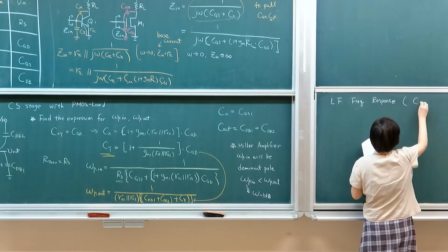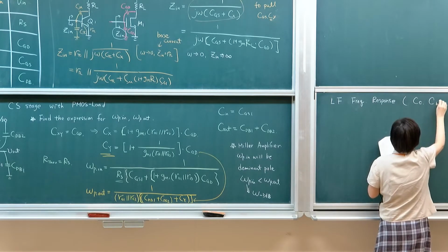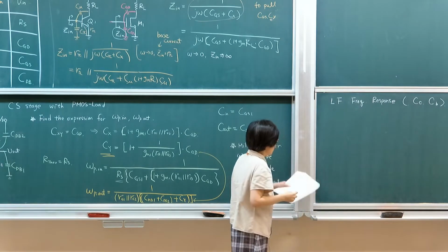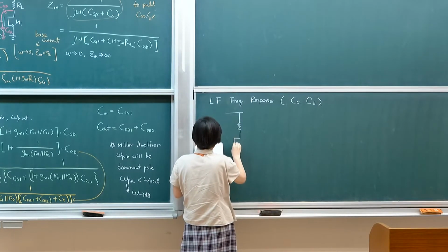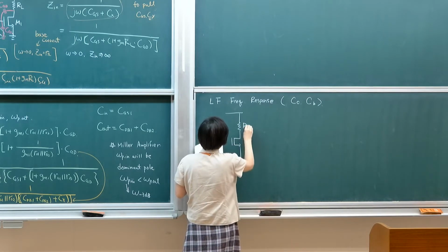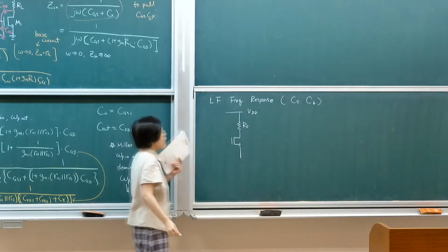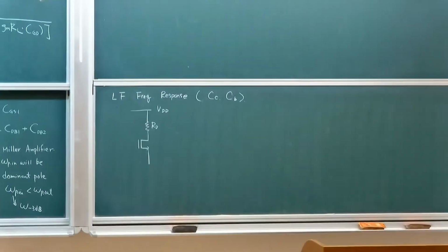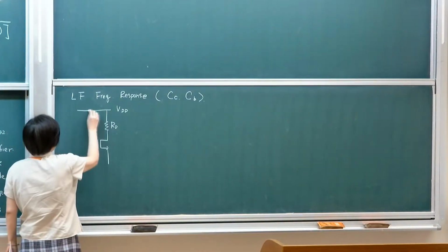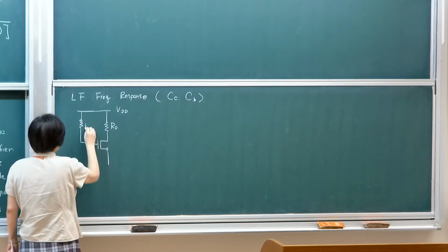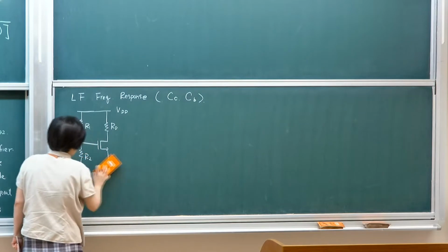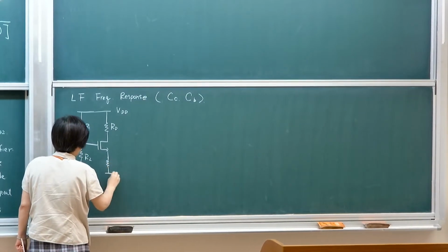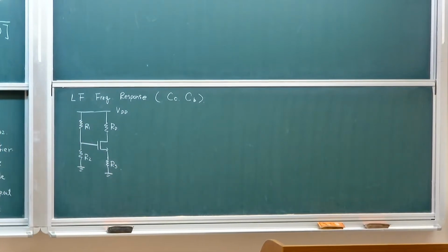As I said, as a result of coupling capacitance and maybe bypass capacitance. So let me give an example. Typically, if we're constructing a common source stage, to set the DC bias you need a resistive network to set the bias. And to further stabilize it, what is typically done is that you add source degeneration.